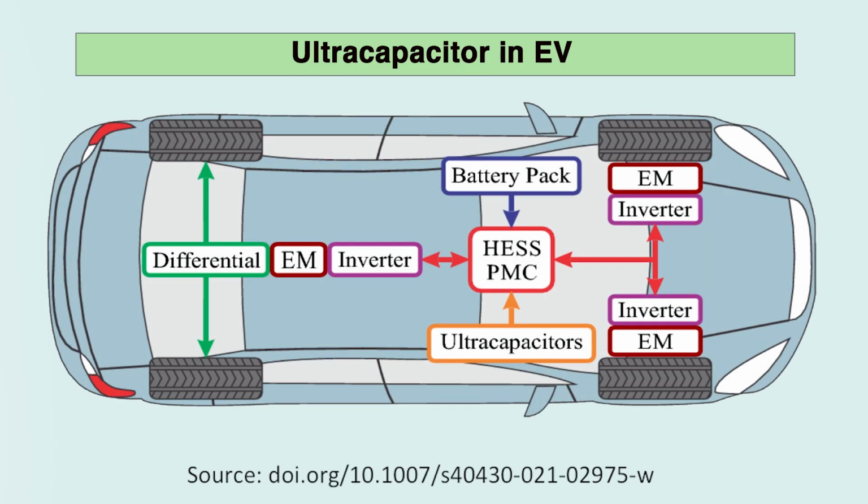So let us understand how these supercapacitors are useful in the case of electric vehicle. In the electric vehicle as well, the primary power supply is the battery. So battery packs are giving the power to your drive. However, whenever a very quick power requirement is needed, at that time the battery is not able to give such kind of high power. At that time, your ultracapacitor is available to release quickly, so that it can accommodate the quick energy requirement of the electric motor.